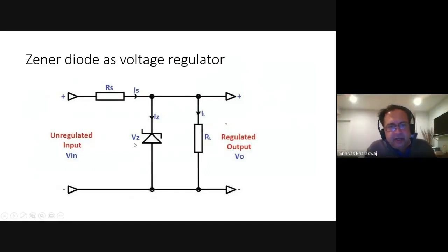When the Zener comes on, avalanche breakdown occurs, and above that particular voltage, it protects the load from the surge of current, which can potentially destroy it. To protect it, they have the Zener, and all the current goes through it.